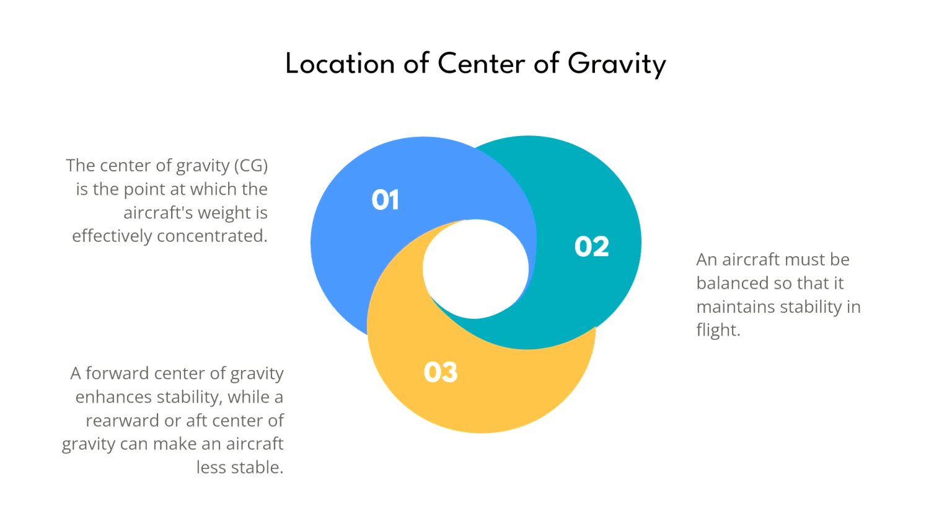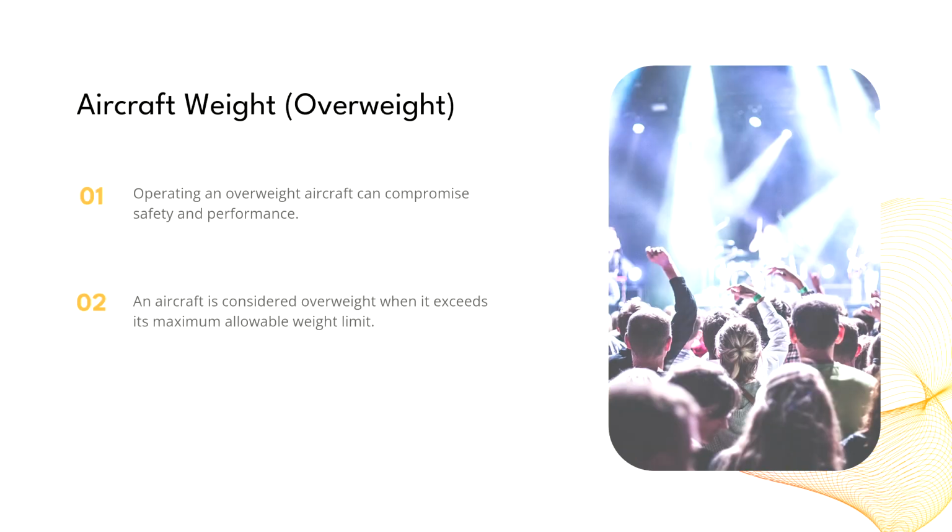While when you have a rearward or aft center of gravity, you may feel decreased induced drag, higher true speed due to the lower angle of attack, decreased longitudinal stability, performance impacts due to lift to drag changes, impossible or difficult recovery from stall and spin, requires additional nose down force, heavy tail to compensate, and an unstable feeling.